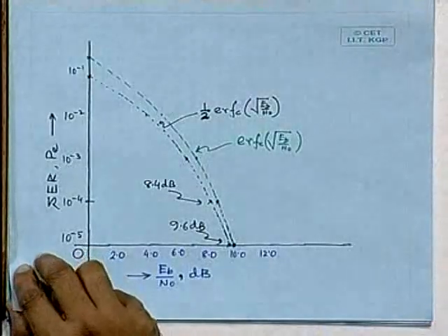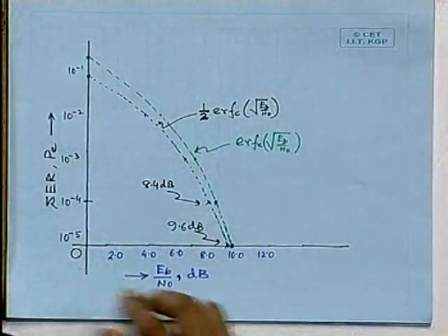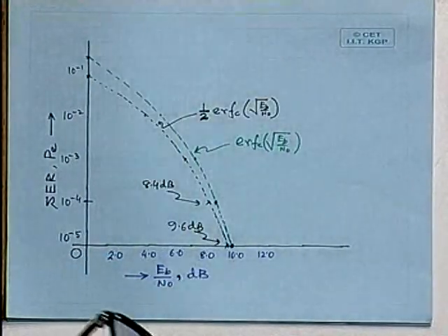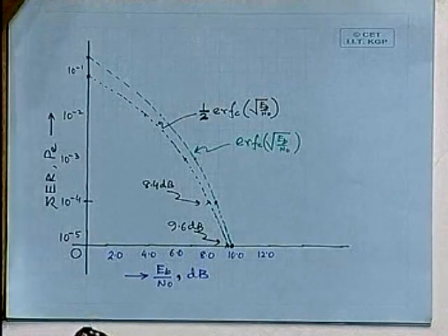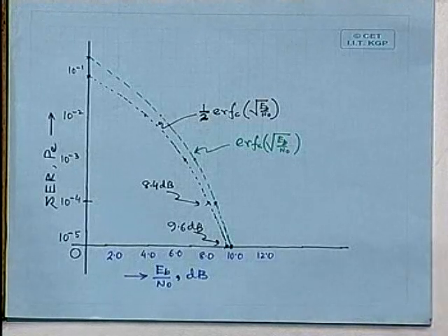The next stage usually is the down converter, the mixer. A passive mixer has loss. Some active circuitry, transistor based ones, are available, many are available really, which avoid this loss too much, but still on the whole you have some loss there. The main amplification comes after down conversion, in the IF stage.